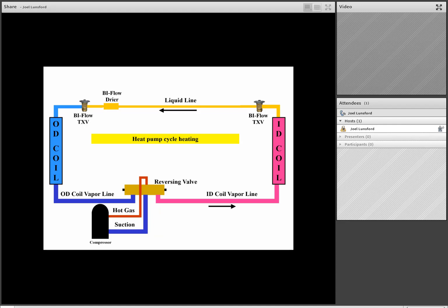So the very unique thing about a heat pump, team, remember, a heat pump allows you to use the refrigeration cycle for the heating mode of operation in the wintertime, but you also use the refrigeration cycle for the cooling mode in the summertime. So the real advantage of a heat pump is it allows you to use the refrigeration cycle for both heating and cooling. In addition, a heat pump is more efficient electrically than just running heat strips.